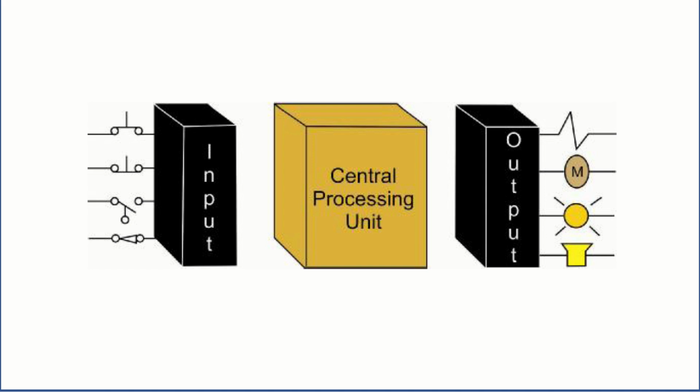And at this point, I ask you to ensure in an automatic manner that the bottles have been filled or not. So if I say you are filling the bottle with Coca-Cola, now Coca-Cola is a black colored liquid. Since it is a black colored liquid, you can simply think of a through beam electrical sensor.